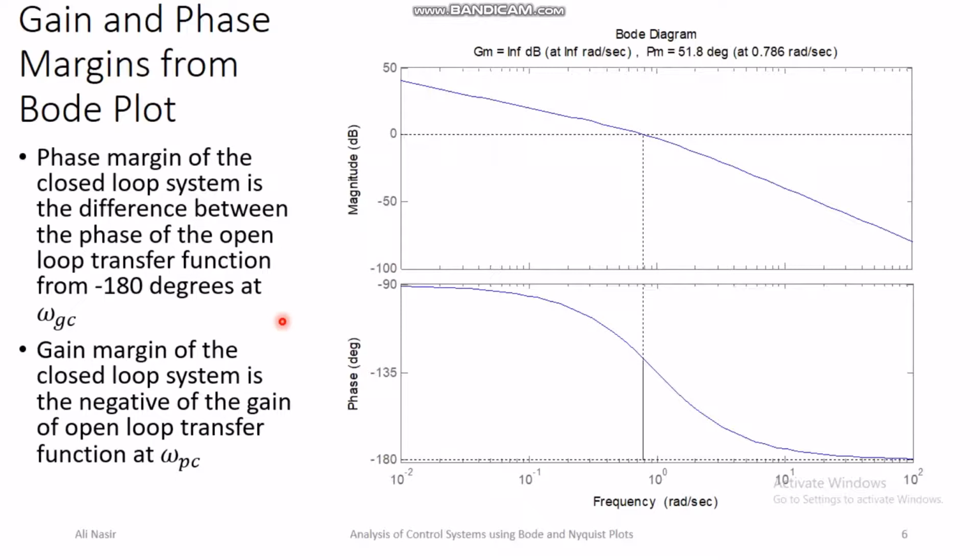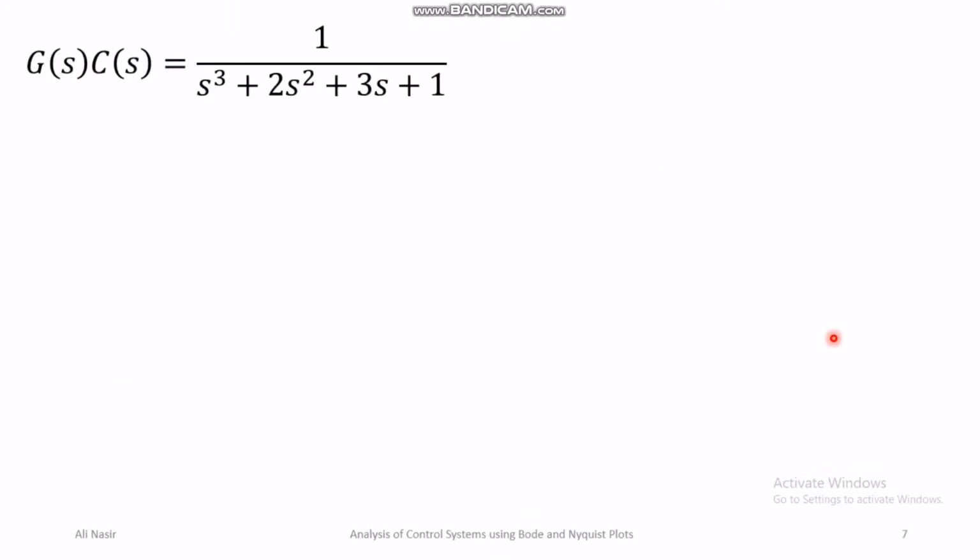If the disturbance goes larger than the gain margin, then that disturbance may cause instability in the closed loop system. Similarly, phase margin is the tolerance against delays in the time domain, or phase difference in the frequency domain, before losing the asymptotic stability property. Next we look at another transfer function.